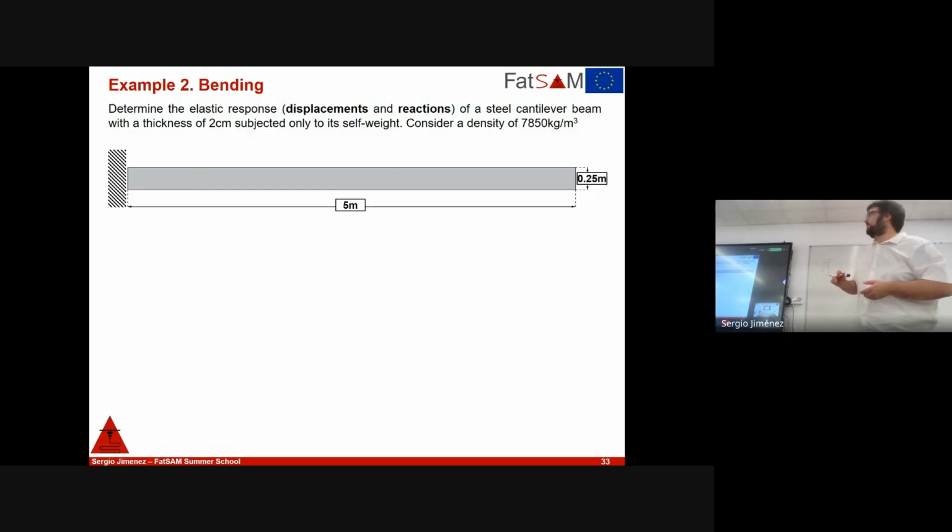Okay? The point is that in the case of the Y, basically the sum of all these punctual forces must be in equilibrium with the summation of all these vertical forces, because the equilibrium must be satisfied in vertical, horizontal direction, and also for moment. Okay, so you should be comparing this force with this reaction, and both must be equal if you are satisfying equilibrium conditions.